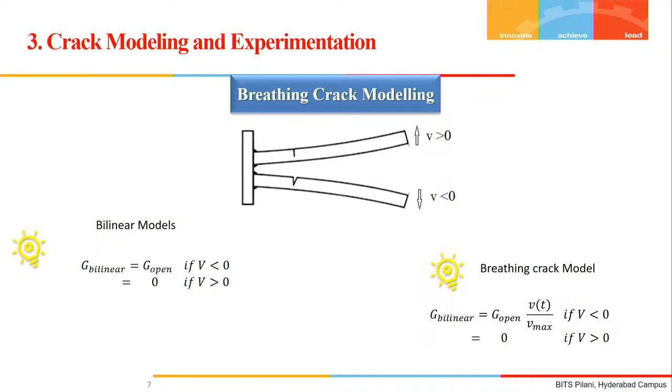If we specifically talk about the breathing crack modeling, there it is assumed that in one half cycle of vibration the crack will remain closed and the beam will be intact, then in the second half of the vibrating cycle, the crack will gradually open, and it will depend on the displacement, and this displacement is coming from the nonlinear equation, so it is difficult to predict.